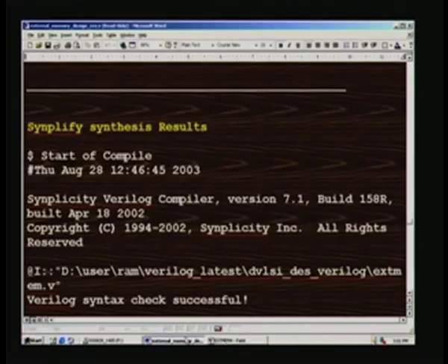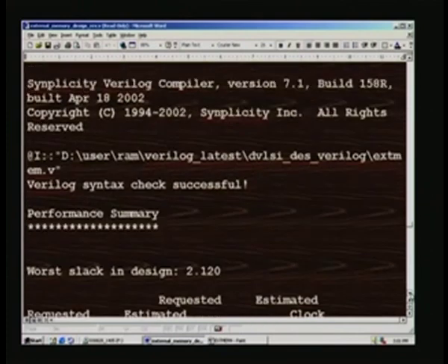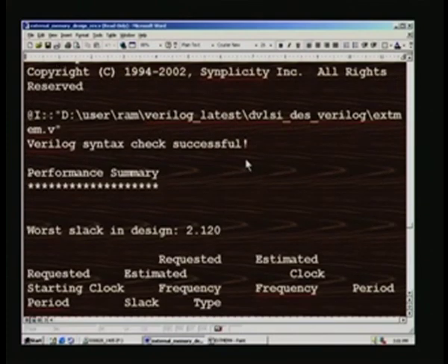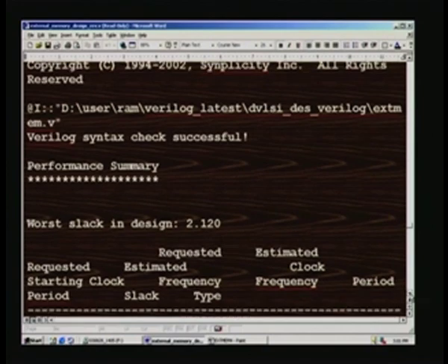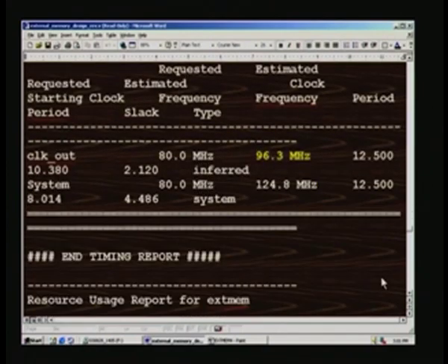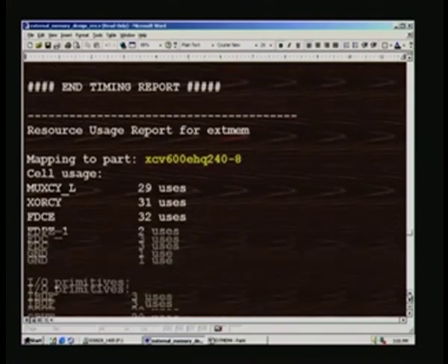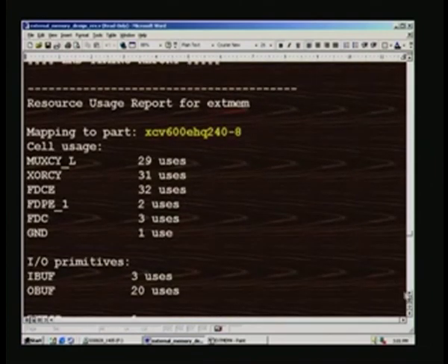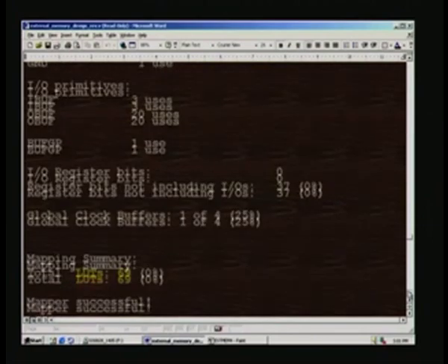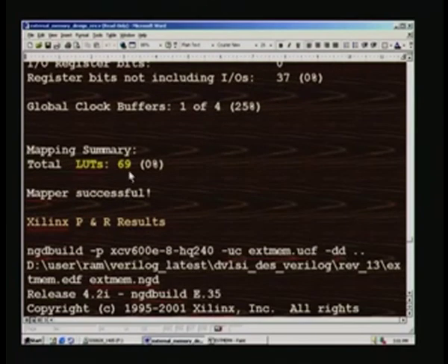And so we will go back to the synthesis results for this external memory, and mind you, the design does not contain the actual memory, it is only a controller. So, you will see that gate count etc. will be less, and the operating frequency reported by synthesis is 96 megahertz with the same device that we have used before, and it has taken only 69 LUTs.